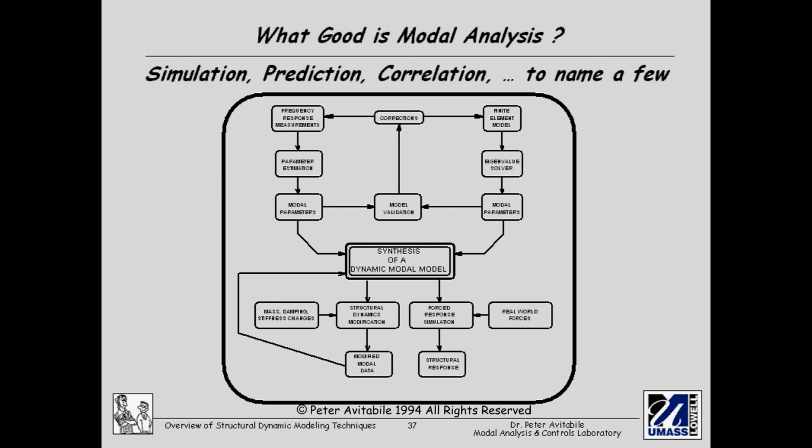So if we said, what good is modal analysis? Well, one of the ways we use it is really for simulation, predictions, correlations. These are a variety of ways that we use this. So it could be that we start either from the testing aspects of frequency response functions and parameter estimation and get modal parameters, or from a finite element model where we do an eigensolution and get modal parameters.